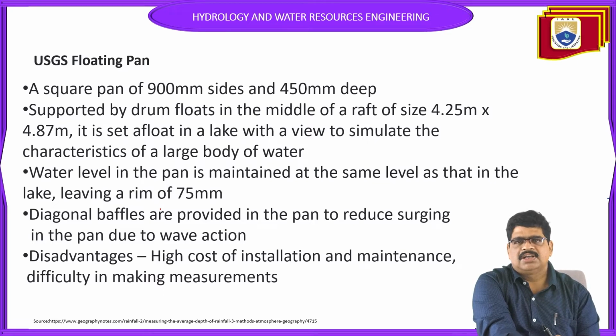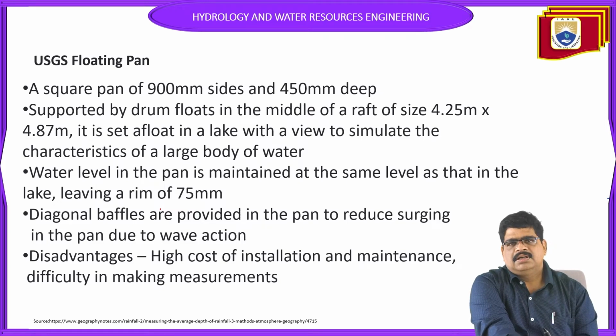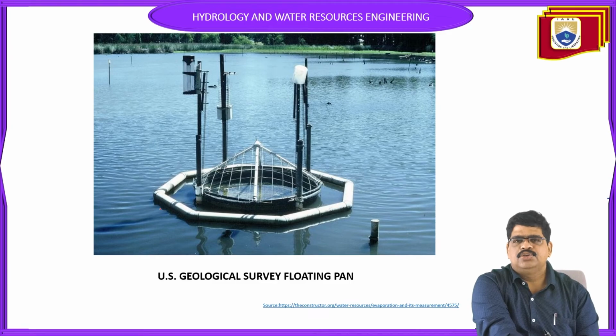Diagonal baffles are also provided in the pan to reduce the disturbance of the pan surroundings due to wave action. So wave action is reduced. Let us see that one. This is the US Geological Survey floating pan. The sides are provided like that to reduce the effect of waves on the sides.